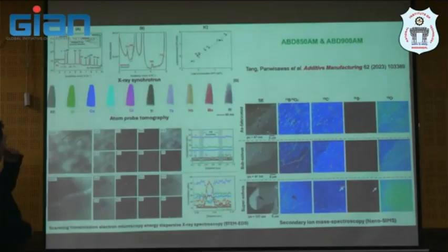So what we do, we suspect why the new design superalloy is crack free. So we try to observe using synchrotron X-ray diffraction imaging at the light source at Harwell in Oxford, in combination with atom probe tomography in the as-printed condition, combined with high-resolution scanning electron microscopy or STEM. And then we do secondary ion mass spectroscopy to understand the oxide in the as-printed condition for these two